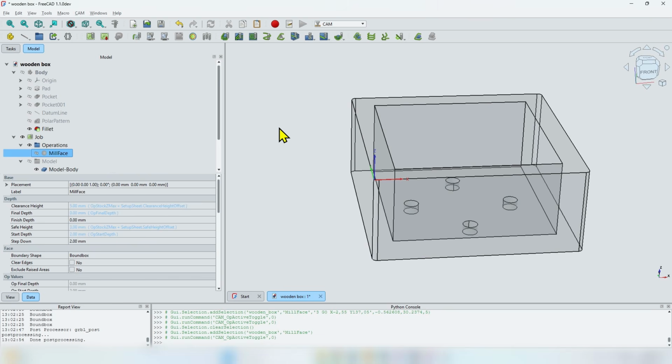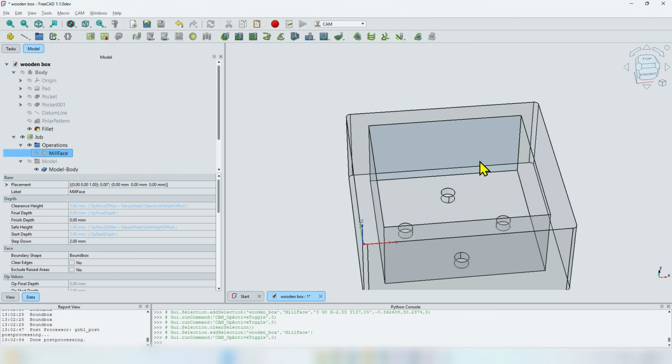In the beginning of the video, I was telling you that I'm going to have a few challenges. One of them is the pretty large depth of this pocket. This is a 54 millimeters deep pocket, which first has a problem because the tool bit that I'm going to use doesn't have such a long cutting height, so I will have to somehow solve that. And I will also have some problems with removing the chips, but for that I will rely on blowing air into the hole to remove the chips as soon as they are cut.